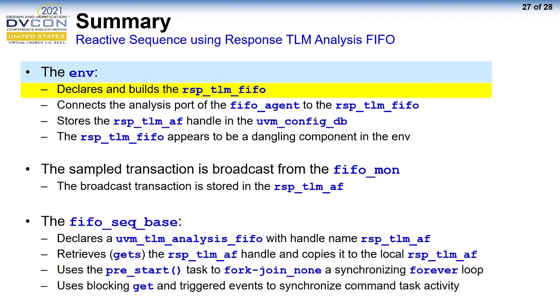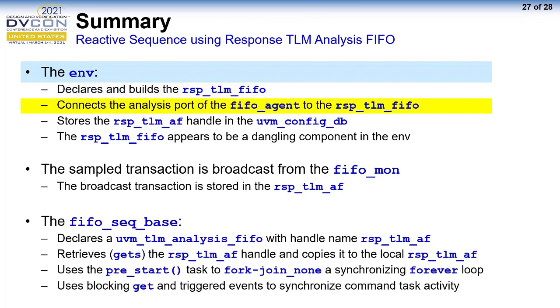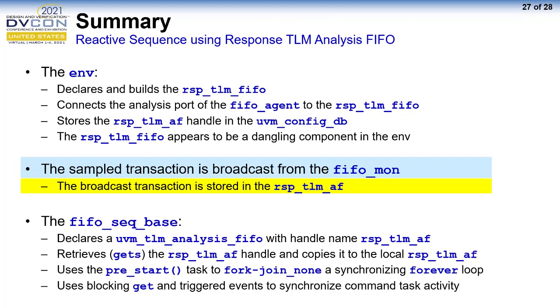To summarize the requirements for this reactive sequence technique using a response TLM analysis FIFO, the environment will declare and build a response TLM analysis FIFO. The environment then connects the analysis port of the FIFO agent to the response TLM analysis FIFO and stores the response TLM analysis FIFO handle in the UVM config DB. The response TLM analysis FIFO appears to be a dangling component in the environment, but it is not. The sample transaction is broadcast from the FIFO monitor and is stored in the response TLM analysis FIFO.